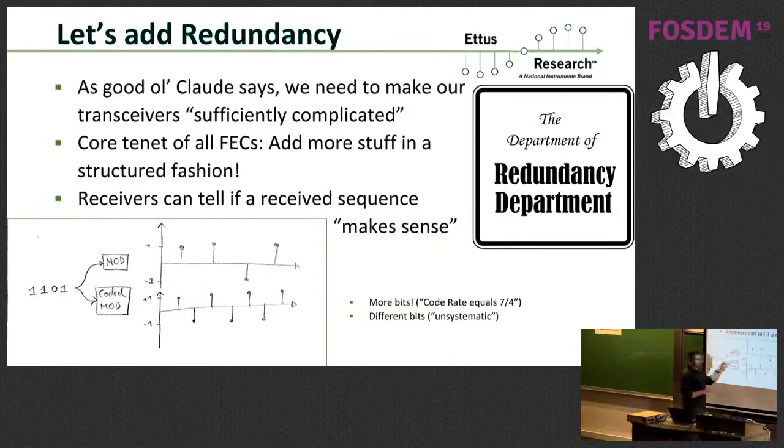put this into some physical representation, I could do this: 1 0 1 0 1 0 1 0 1. And you'd say, well, wait a minute, that makes no sense. This bit sequence is not in this bit sequence. And I said, so what? I'm making up my encoder here. As long as my receiver knows that 1 0 1 0 1 0 1 0 equals 1 0 1 1 0 1, I'm done.